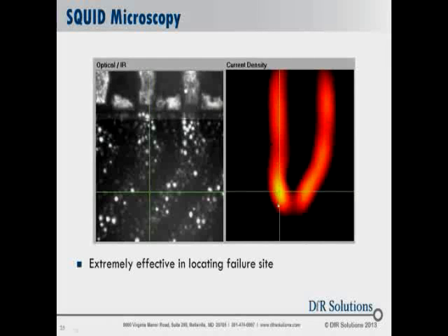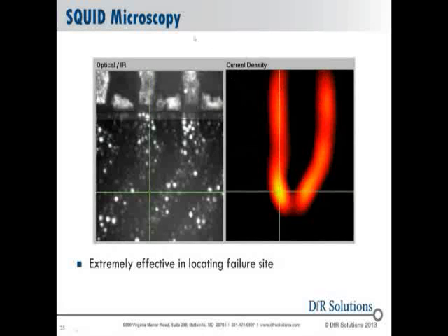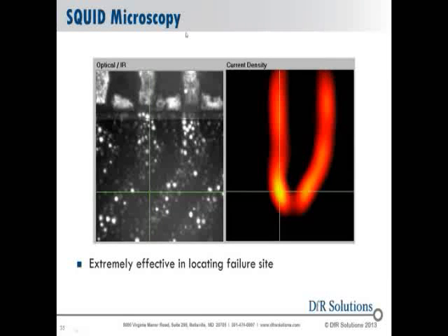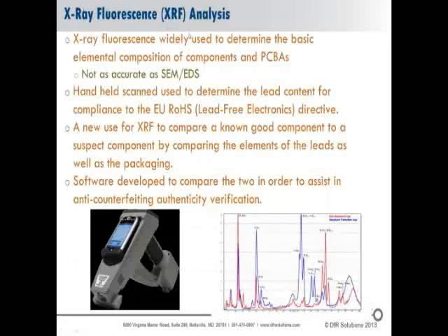So this is not widely used yet. These are used very sparingly, but they're another new and exciting technique that's out there. X-ray fluorescent analysis. This is using quite often a handheld X-ray gun, which excites elements and gets them to send back a spectrographic pattern that can be used to identify the kind of elements that are in a material.